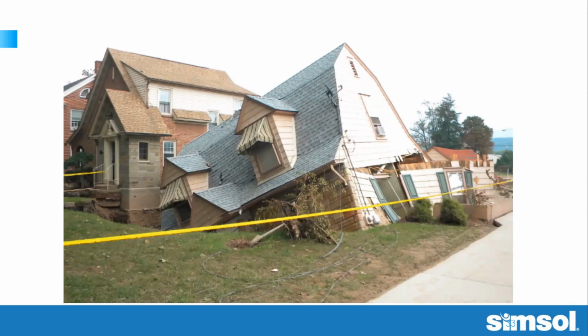I have a question for you. Sure. Since you mentioned it was flood, but could it also be sinkhole? Not in this part of the world. In order to determine whether or not it was a sinkhole, we'd have to do geotechnical testing, which would involve drilling to determine what's going on underneath the ground surface.